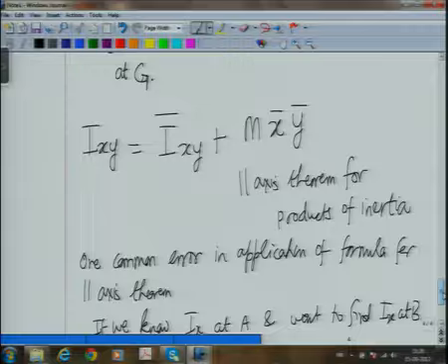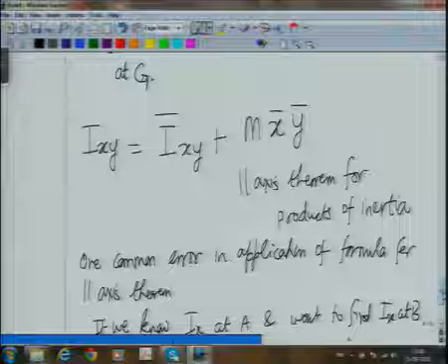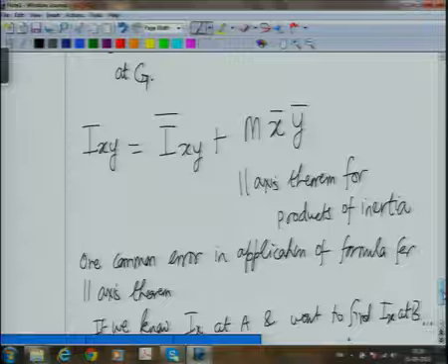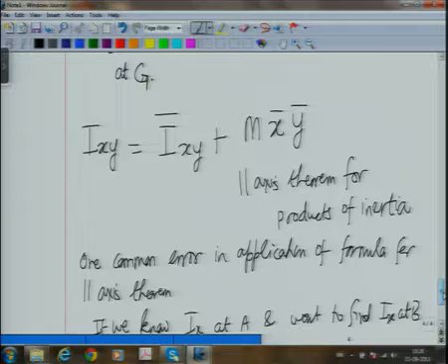Okay, so the best way of applying this formula is, see, till now you have done only planar sums. So wherever you applied this formula, you just looked at the physical problem and calculated the distance between the two axes. But in three-dimensional problems, calculating the distance may not be so obvious. So the best thing is, if you are shifting along all three axes, you just use the formula blindly.